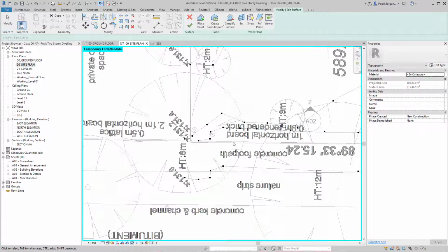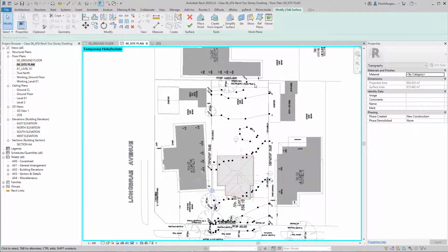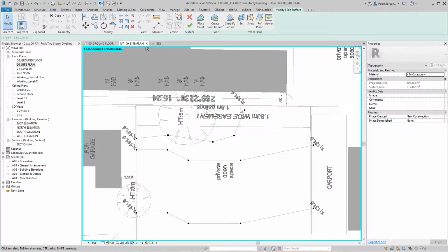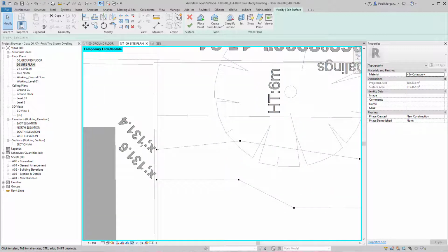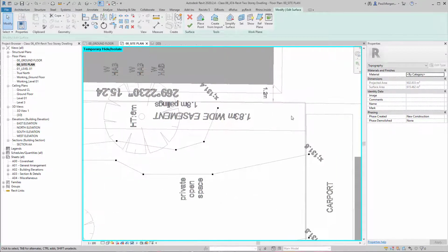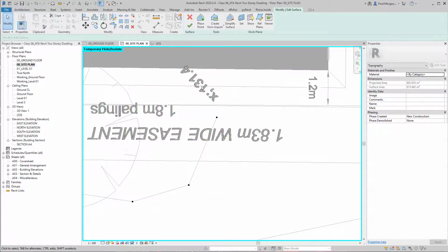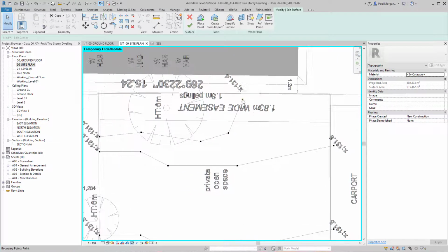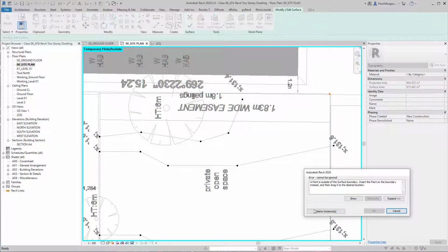I can go back to my site plan and we can add more points after the fact too. So we only have contours back to here. Unfortunately, we don't know what these two last points are here. 131.4, it's on its way down back to the back of the property. That's 131.4, and that's got a contour. So I'm just going to place two more points, and I'm going to call them 131.2, just as an example. And I'll place one there.